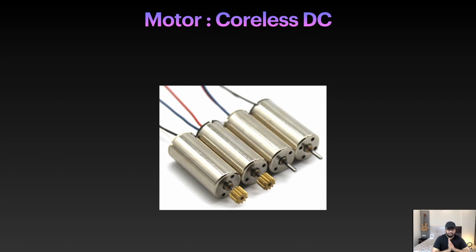They can run at a very high RPM and are mainly used for indoor drones. They don't particularly have a good lifespan or longevity, but that is not an issue in indoor drones, and they are really cheap, so you can replace them easily. So just for your knowledge, this Coreless DC motor also exists, which you can use in your drone project. More specifically, they are used for smaller indoor drones.